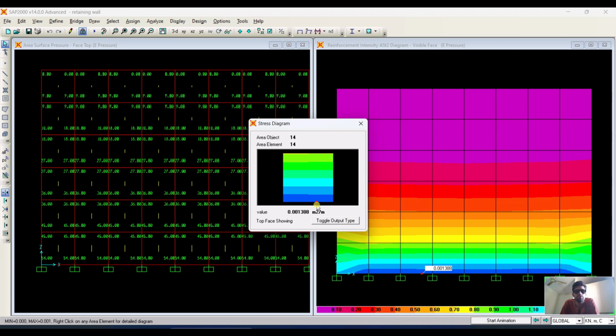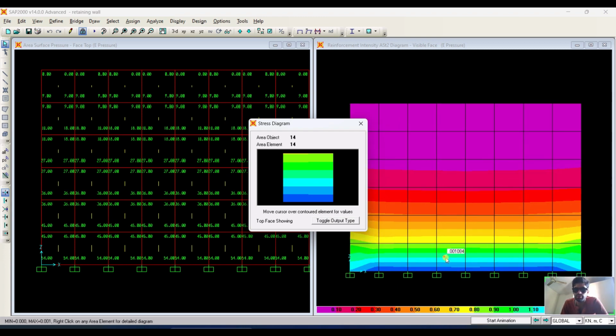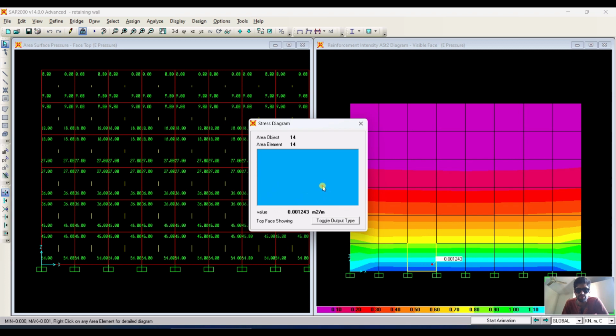You need to consider strips: column strip, middle strip. SAP is reliable, and SAP has the option of using middle strip and column strip, so it will be a strip-based design, not a finite element based design. You can also take one, two or three cells from this point, and do those cells in an Excel calculation.